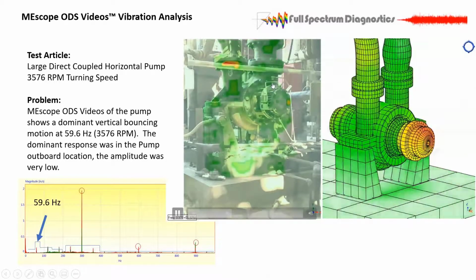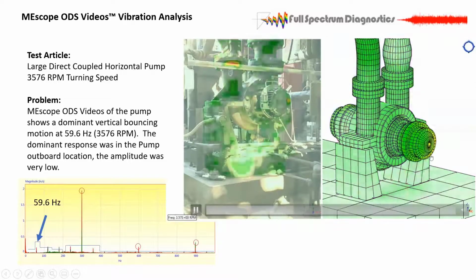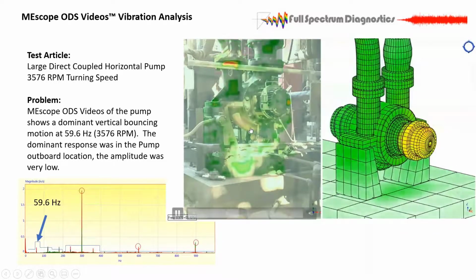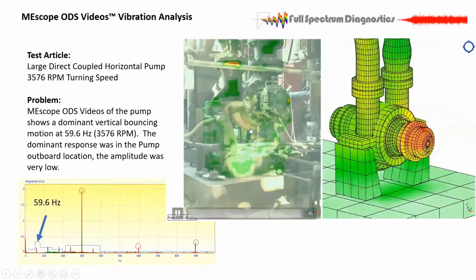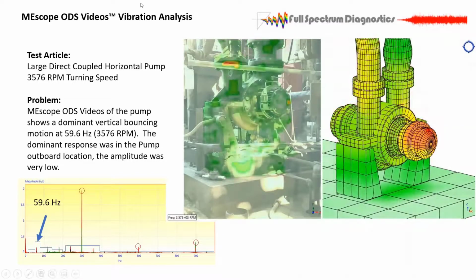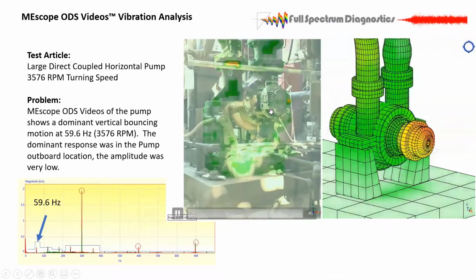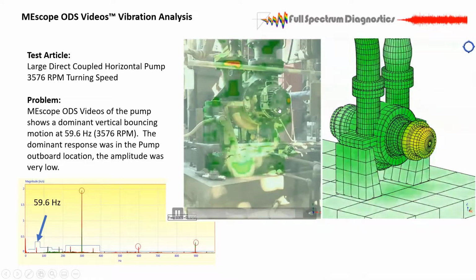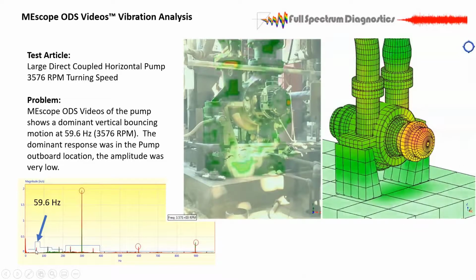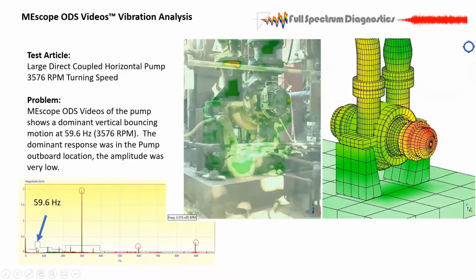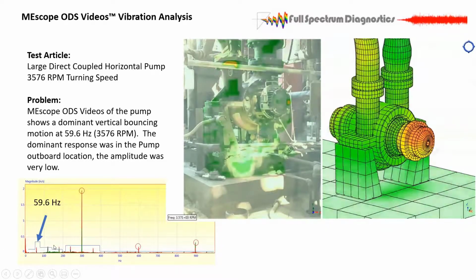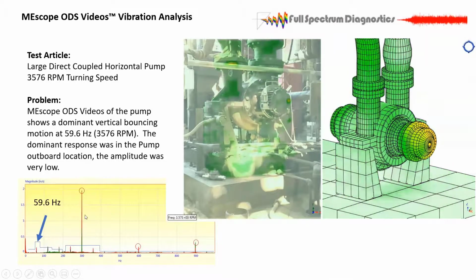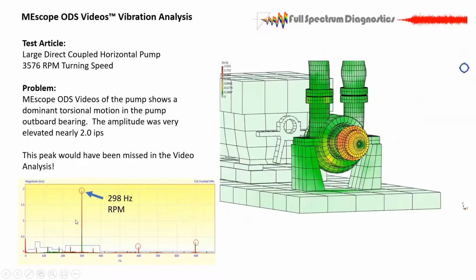They were in different conditions when this data was taken compared to this data. They had some pressure loads that were different in the pump at high performance, and I think that's what we were seeing here. So there is a little bit of vibration. When you look at the scale of things, it's only about 0.15 inches per second. So it's pretty small compared to the blade pass frequency, which is right here. So the blade pass frequency, when we animated that, that's where the interest really started peaking.